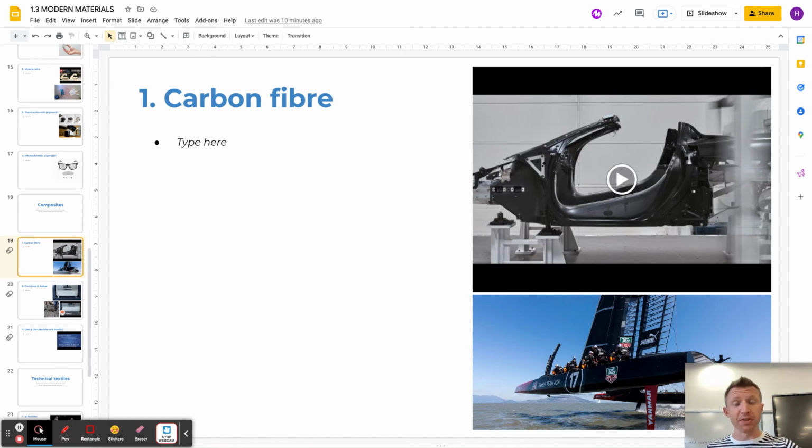So when that happens, you have to have the entire segment of that piece of car replaced. If it's the chassis, that could end up having fundamental cracks, fractures all over the chassis, so the whole thing would have to be scrapped, and then you'd have to get a new one. So it's terrible for recycling because you can't separate the materials, and it's terrible for repairability. So that's just something to bear in mind with carbon fiber.